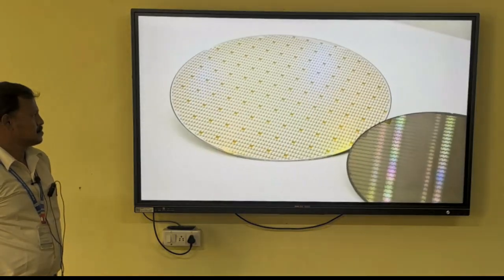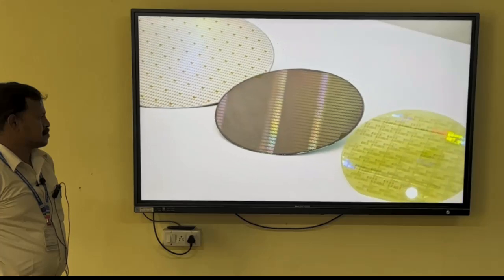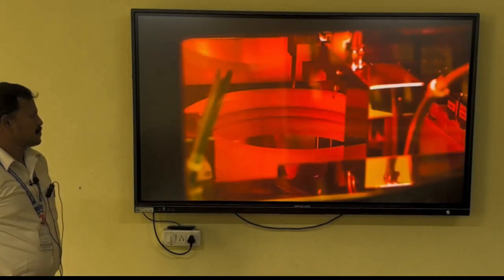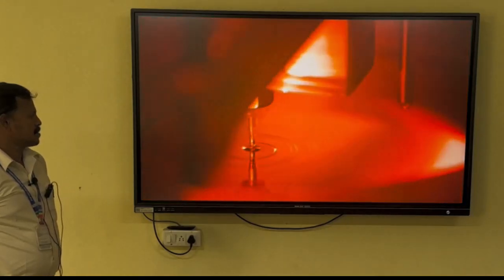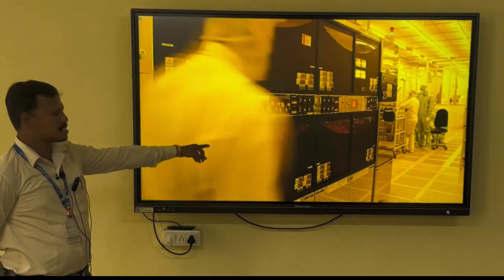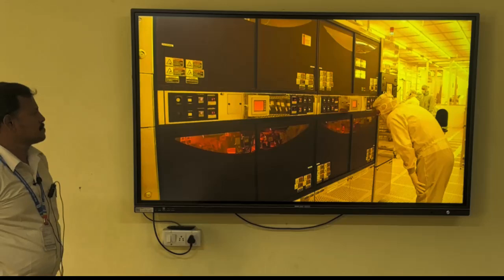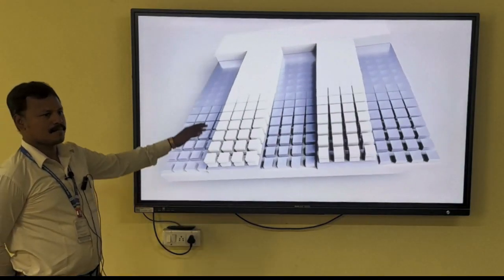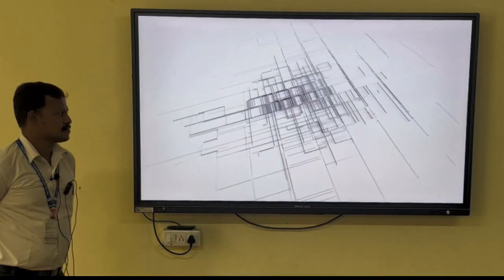In our clean room, up to 35,000 chips are then made from each of these discs. In numerous process stages, the wafers are given their characteristic surface structure. After coating with a liquid layer, the wafer surface is exposed, developed, and etched. This results in the desired conductor structure. The masking and etching processes are hundreds of times finer than a human hair.